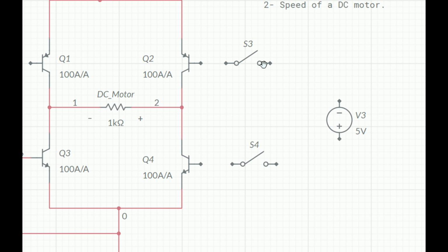So if it is connected to the ground, this transistor will get triggered. Once it gets triggered, it is connected to the positive side of the circuit, the same as done with the switches. This path opens, this part gets closed, and we will get the positive at this end. So right now we want to bring positive here and negative over here to make the motor move in one direction. So I close this switch. Now it got the negative from the microcontroller, or we have given 0 to the PNP transistor. So now it's triggered, and positive is at this end.